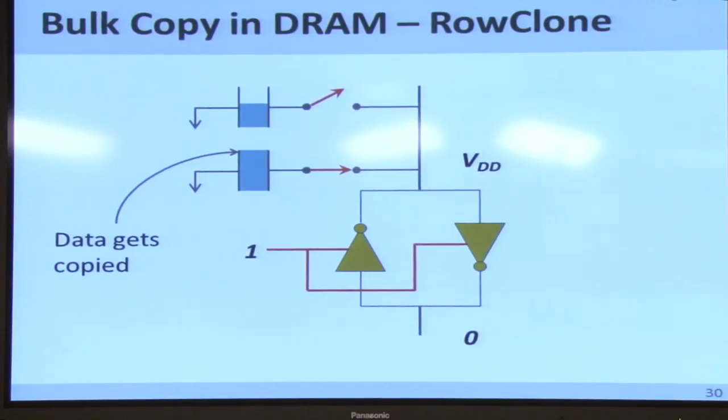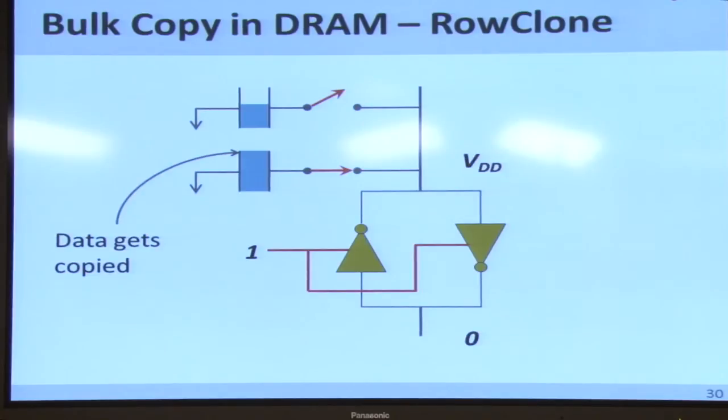I think there's an internal FSM running once you get into that state. In order to get out of that state, you have to go through a pre-charge. So in this particular case, you have to issue an intervening pre-charge. But we haven't tested that. There are other issues as well, which I don't want to get into. For increasing yield, they may map a faulty row of one subarray to a row within some other subarray internally, right? Again, our mechanism wouldn't work in that case.